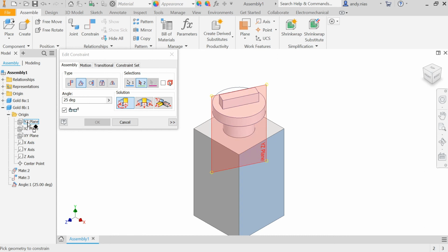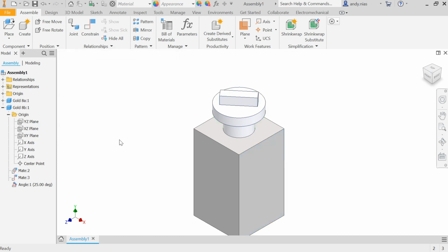one of the planes. So again, as I did before, I could pick up that plane, or I could pick up this plane here, and I can set an angle between them. So I could make it wherever I like. If I haven't got a feature on the part that I can select that's flat, I can always find the planes and use them instead. So that's the Orientate constraint, which allows us to set parts off each other at a given angle.